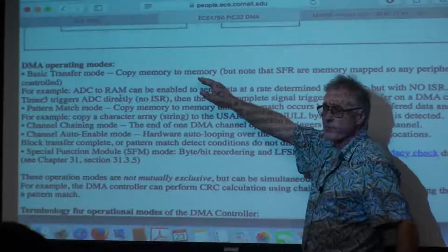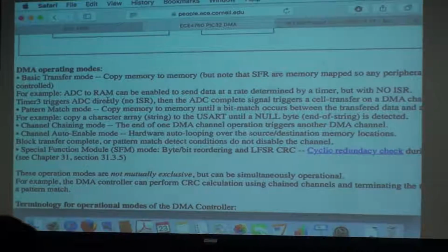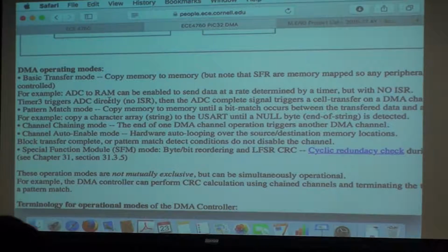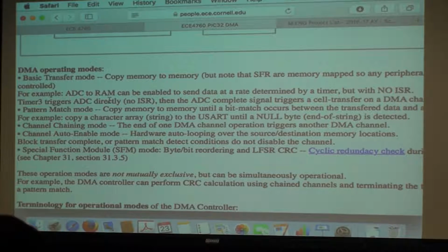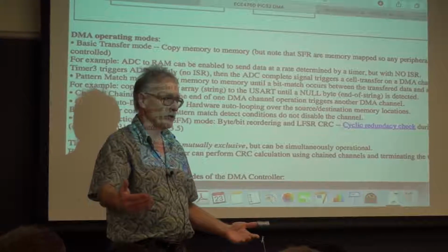You've got your basic transfer mode, which is what I've been talking about, which is memory to memory. But remember the special function registers, that's code word for I/O, like timer registers and other memory locations, are memory mapped so that any peripheral can be read from or written to.